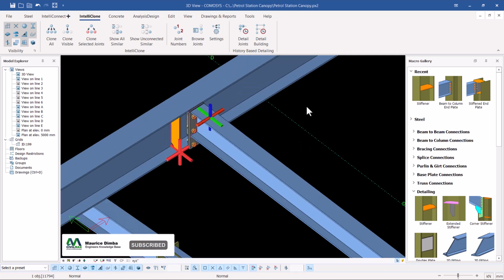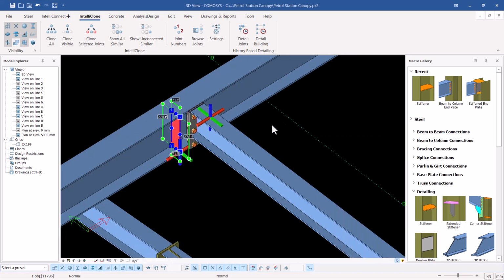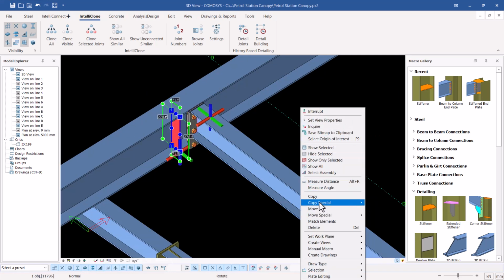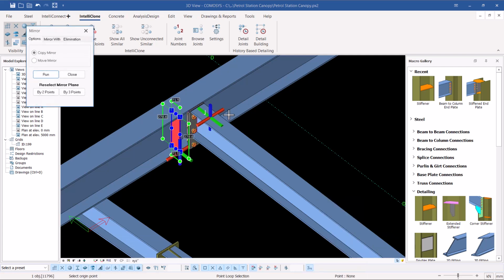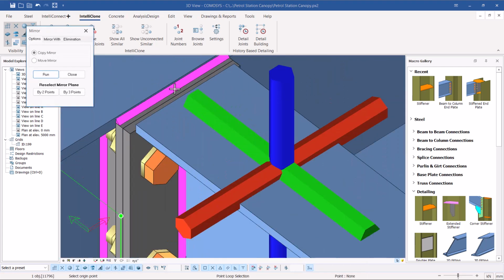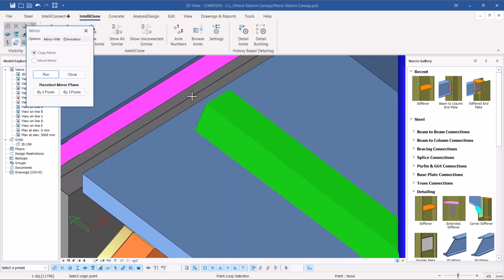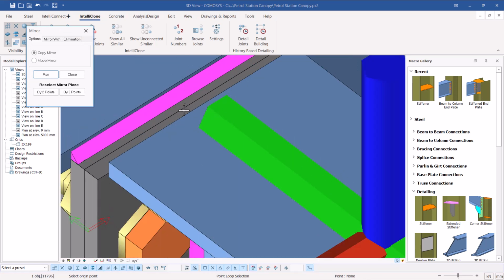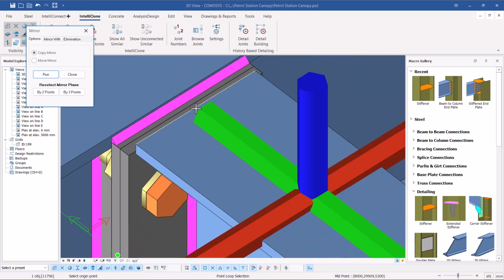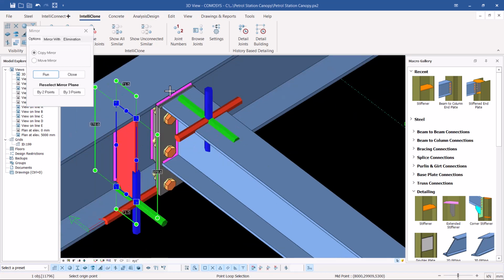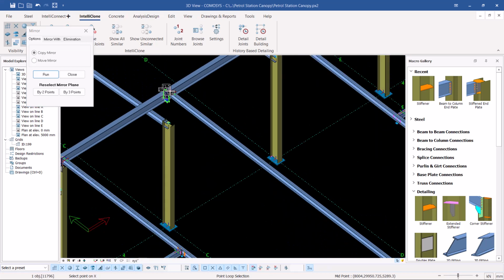and once I've done so, I'm going to right click, select and right click and mirror it on this far end, and pick and define a mirror point here. And the moment I define a mirror point here, I'll be able to just snap at the center here. Let me just pick a point that will be able to snap accurately, and that is the point I intend to snap on. And it doesn't matter the length.